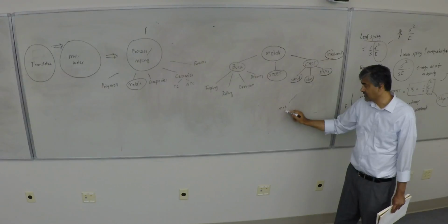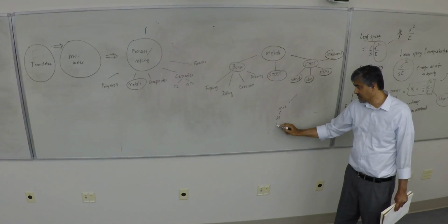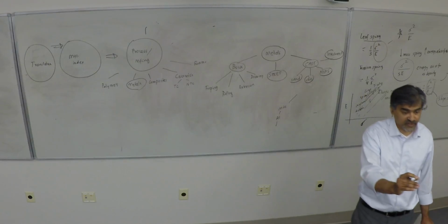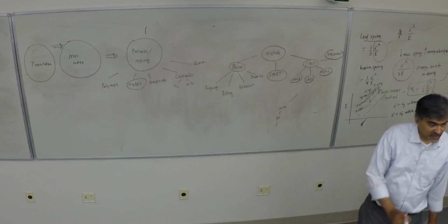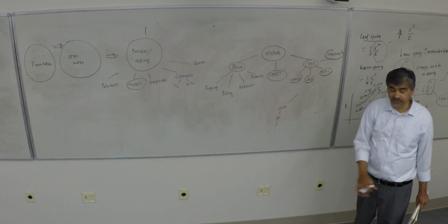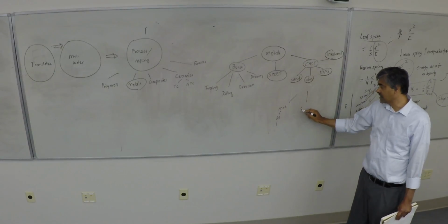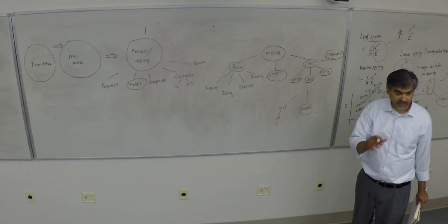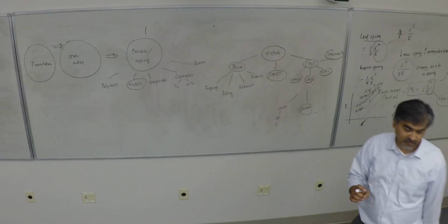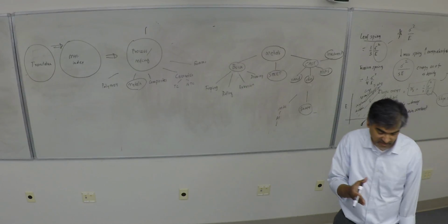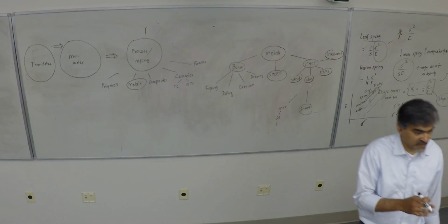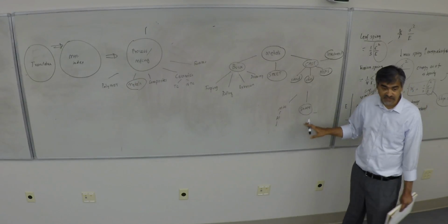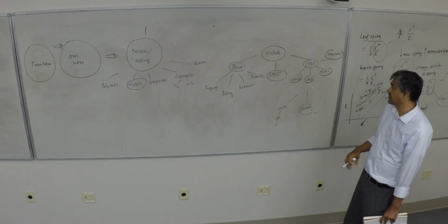If you look at material, I'm going to use aluminum. Within aluminum, I have 20 different alloys that I can work with. So I can really zero down into the specific level of alloy based on knowing what approach is going to shape. The other thing we'll talk about later is what should be the shape of it. What are the effects of shape? To get the same part to do the job, but how should I shape it? Should I add a rib here, or should I add a bend here? Should I add a step here? Or should I make it a big monolithic block? All that will dictate my shape factor, which I have not looked at here.